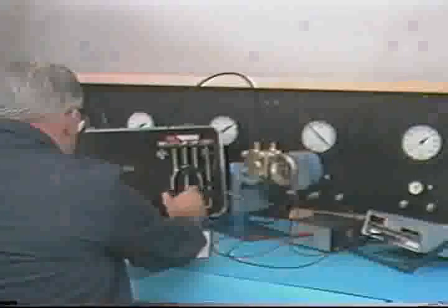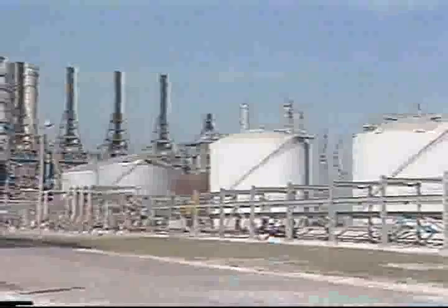We've seen that in open tank applications where a differential pressure transmitter is used to measure level, a low-pressure calibrator can be the input standard. In setups like these, the process liquid's specific gravity and operating levels of the tank are used to determine the instrument's range and ultimately the test points used for calibrating.